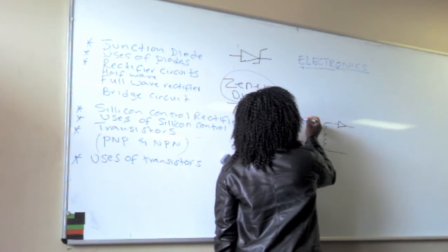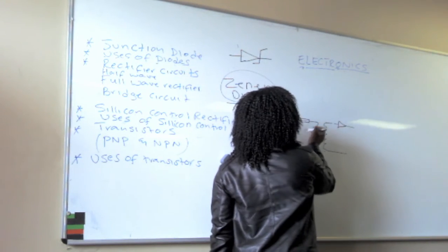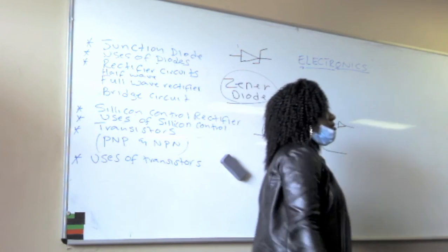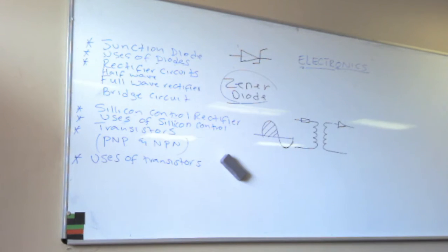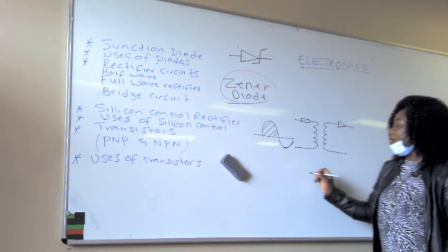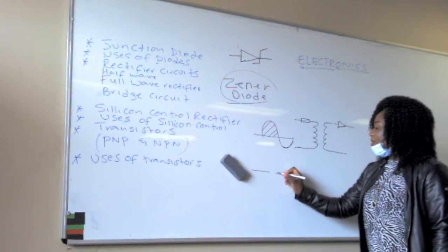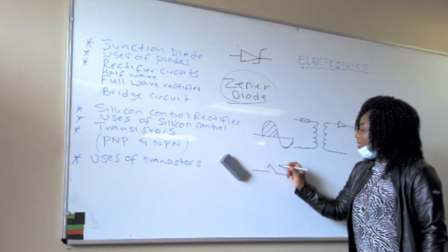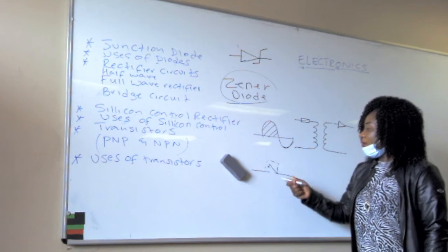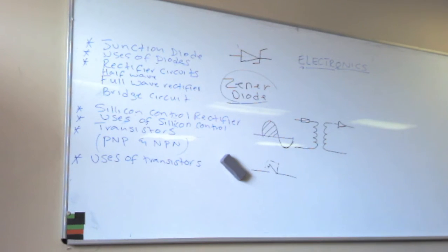And then some examiners want you to draw this sketch. Maybe they'll say put a fuse here. This symbol is a fuse. A fuse has got a line across it. A resistor has no line crossing over it. So don't confuse a fuse and a resistor. So if the examiner says on the primary side of a transformer, show a fuse, or show a circuit breaker, which I'll show later. For a circuit breaker, you need to have a wire and a wire, and then you do that, and then you do a star here, and then you do lines like that. That's the symbol for a circuit breaker.